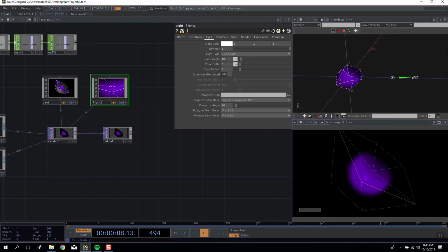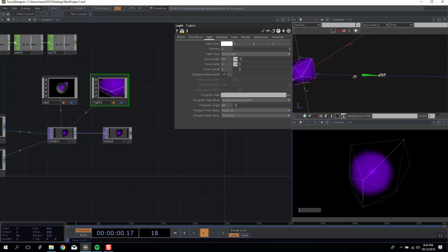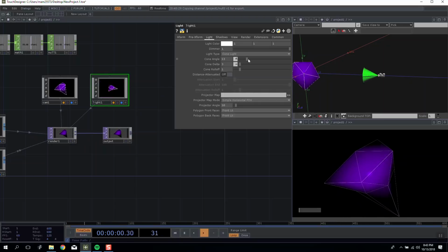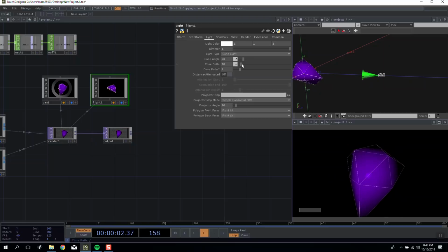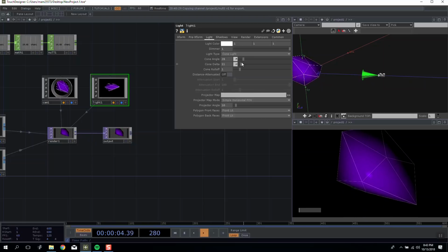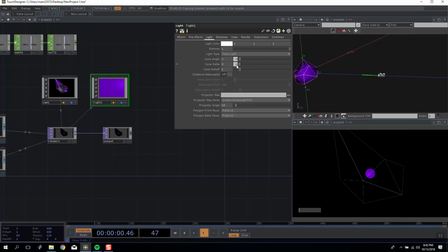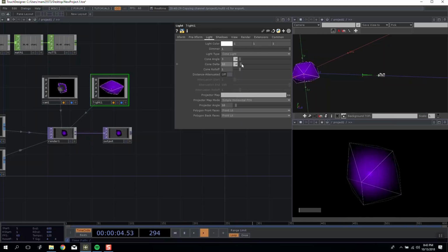And instantly, the reason the geometry viewer is so helpful is because it explains what this is doing. It went from being essentially a light bulb without a cap to a light bulb with a very direct cone of focus. A cone that we can make wider and shallower, and then increase what is called the delta. So basically the feathering on the edge of the light. So if I make it super tight and turn my delta all the way down, you see it get pin sharp. Turn up the delta and it starts to roll off.